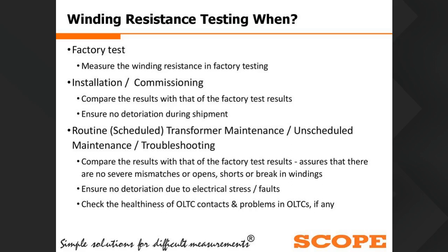Then, it ensures there is no deterioration due to electrical stress or faults, and checks the healthiness of the OLTC contacts and problems in the OLTC pin. So these are the reasons we need to do the winding resistance test in factory testing, during commissioning, and during routine testing.